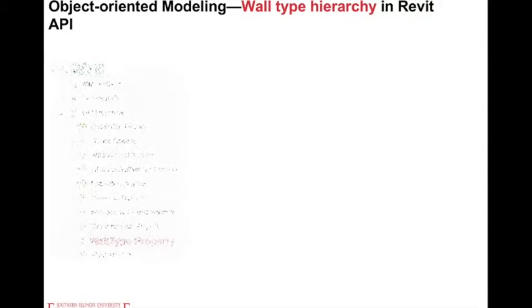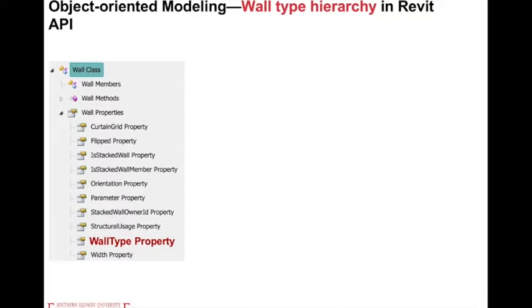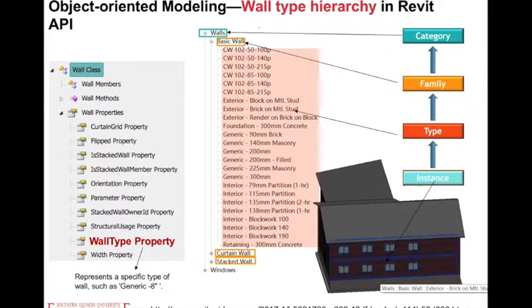The next topic we talk about is the wall type hierarchy, which is here, wall type properties. Generally speaking, we need to have a hierarchy order to organize different kinds of walls and put them into different categories, to help us quickly find the most common parameters and group them as subgroups. So this is an example, a hierarchical tree I showed here.